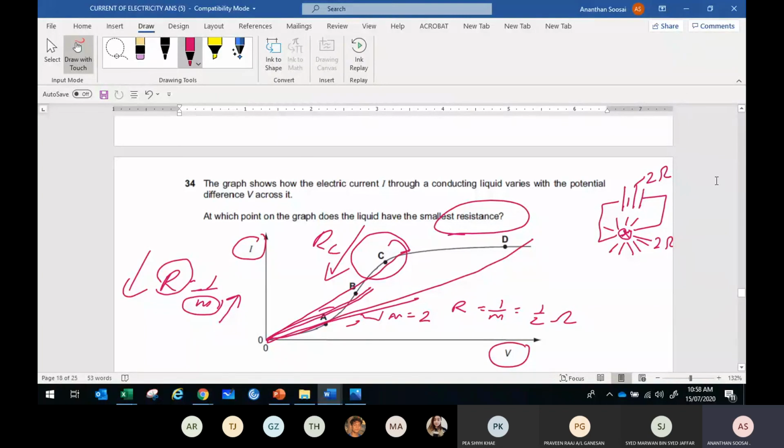So all of this is a manufacturing limitation. When a battery is made with 2 ohm, the light bulb will be made with a different resistance. If you use the light bulb with 2 ohm resistance, the light bulb will have maximum brightness. The maximum power will be dissipated. But normally when you purchase a battery, it will have its own internal resistance. You can't change it. You buy a light bulb from the shops. So the brightness you get from the light bulb is not actually maximum.